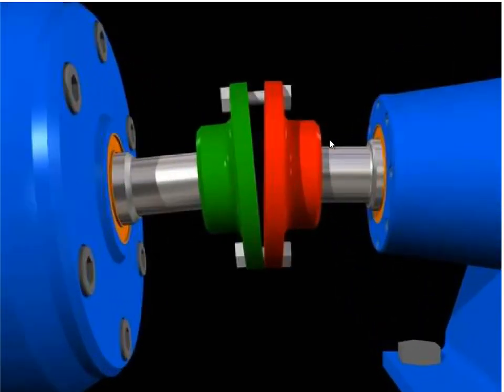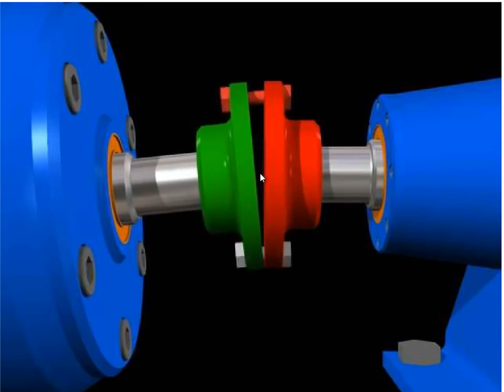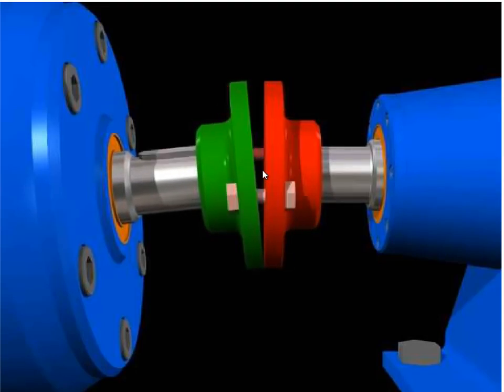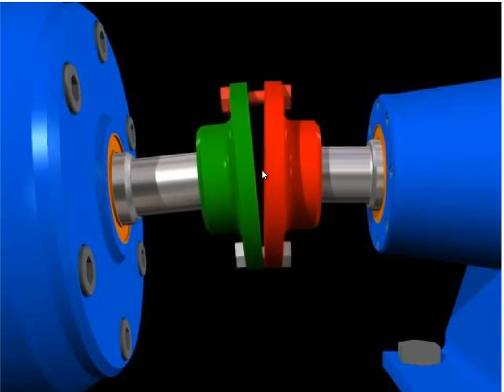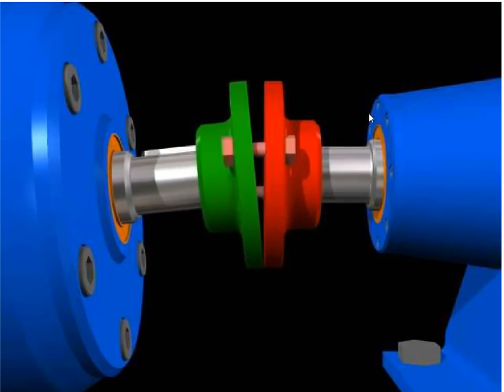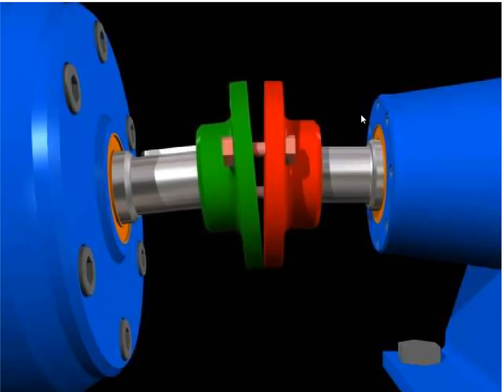With angular misalignment, not that you can see it, ignore that key, it's like pushes, pulls, pushes, pulls. We get axial vibration and we see a phase difference between this face and this face. We have to adjust them because we're pointing the sensors in opposite directions, but we will see that 180 degrees phase difference there.